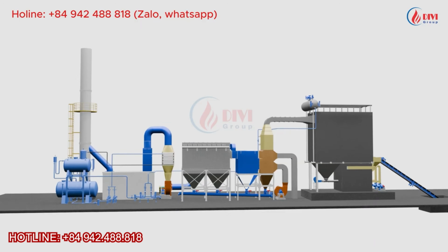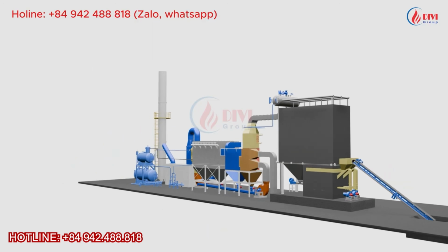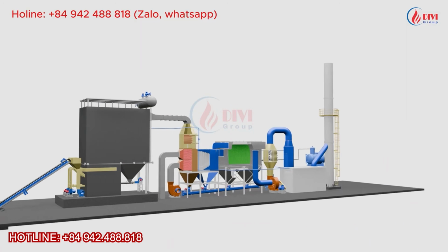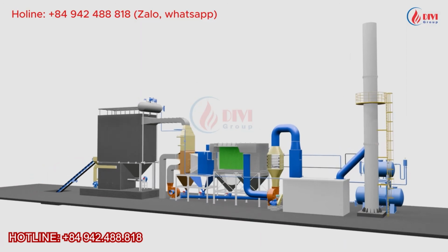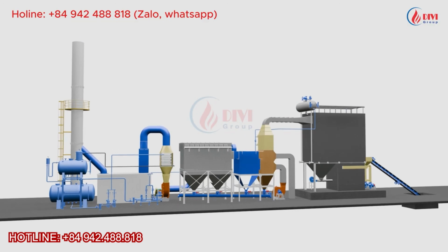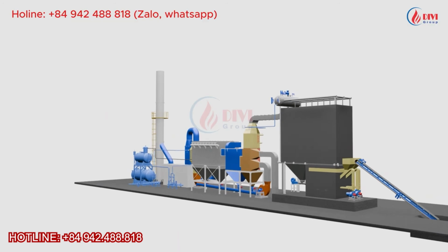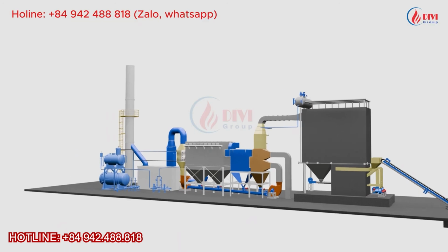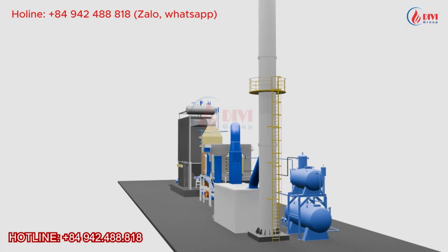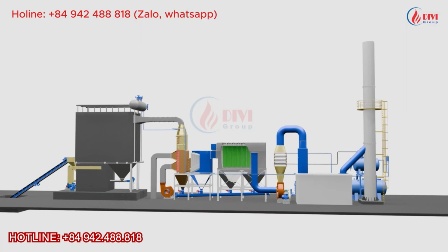To summarize, if fast steam generation is your priority, the single-drum water tube boiler has a clear advantage. With a well-designed layout, cleaning can also be completed quickly, reducing boiler downtime. However, when operating conditions are poor, water treatment is inadequate, or blowdown is not performed regularly, this design is generally less tolerant than a combined water tube and fire tube boiler.